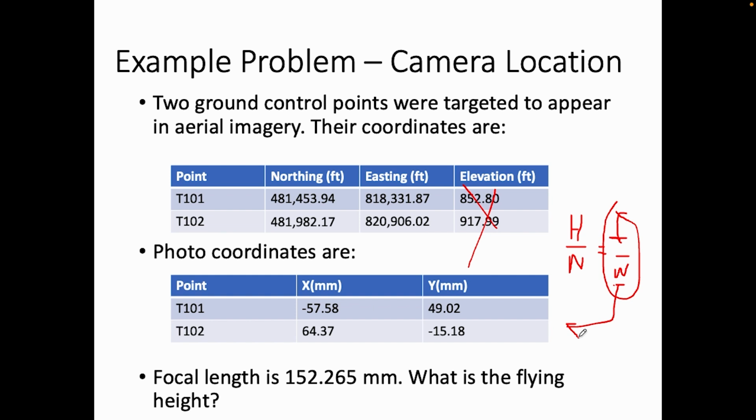So we'll take these numbers, and I've done the math here already, but like I said, pause the video and work this out yourself. First, we've got the square root of, what's this going to be? Negative 528.23 squared plus negative 2574.15 squared. That's going to be the square root of a big number, 6905275.15. And that's going to give us a final distance between these 2 points of 2,627.79 feet, approximately.